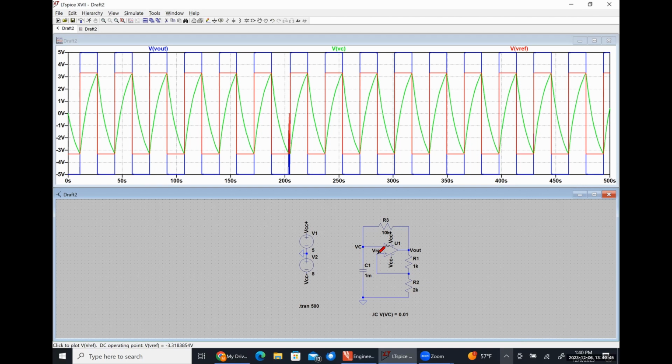We would tie, this would be our offset node. And then we would usually tie this to a secondary gain stage, where that gain stage will probably be an NPN-based common emitter amplifier. That's just going to give us a very large inverted gain. And we would do a PNP stage so that we have headroom. We're going to talk about all this electronics next week, by the way. But effectively, this is going to have some stable DC operating point. If this was 5 volts, this would probably be somewhere in the ballpark of 3.8 volts or whatever.